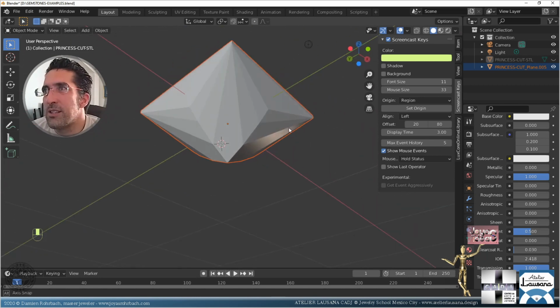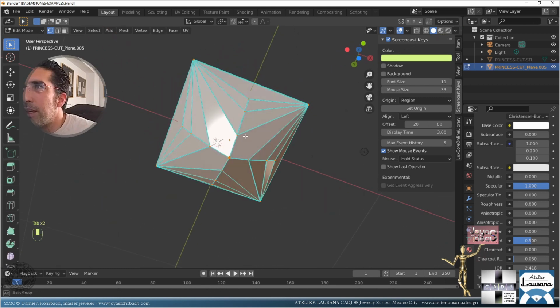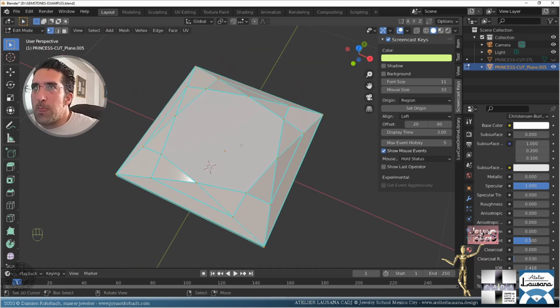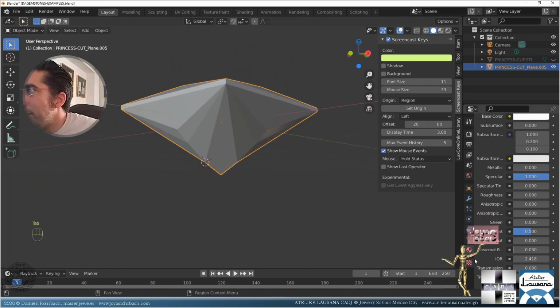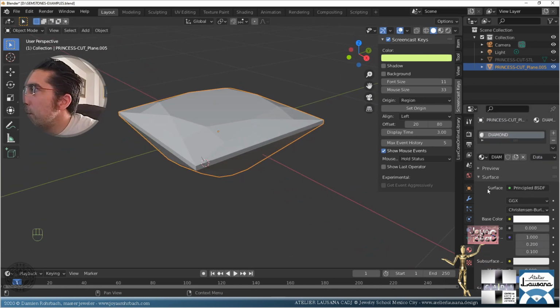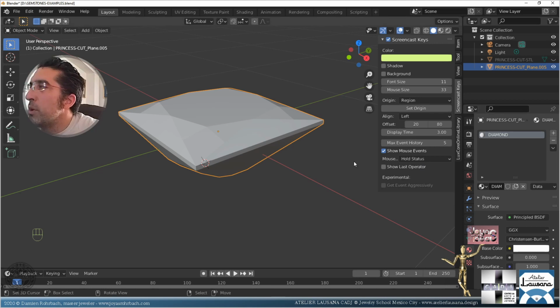First main difference is that the OBJ file format doesn't change the faces. That's why I prefer the OBJ file also between softwares, because if you're going to make the render using another software or design something else, I prefer the OBJ format because it won't change the cuts of the faces, and that's very important for these models because, again, this asset has real faces for the gemstones. So if we want, and generally we do want that kind of realism, we want the original faces, so that's important. And also let's go to material, and this one already comes with the material, which is